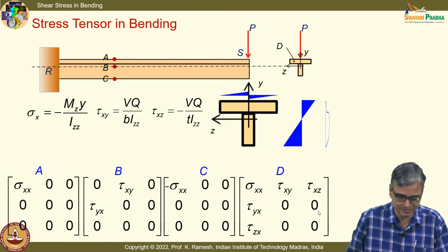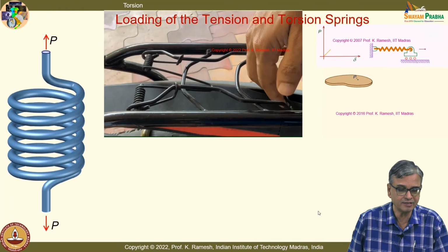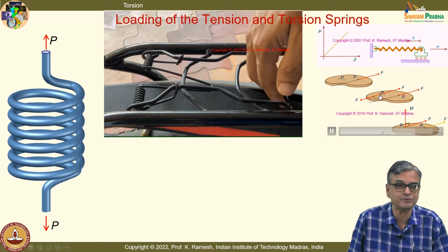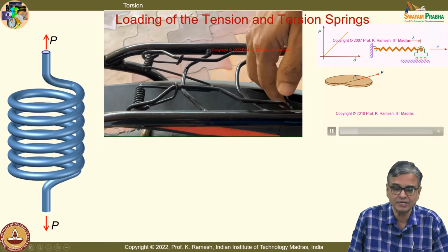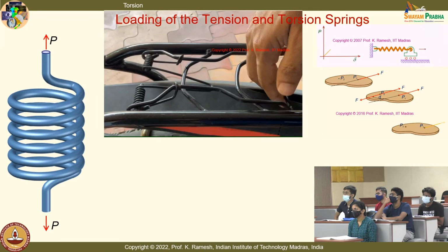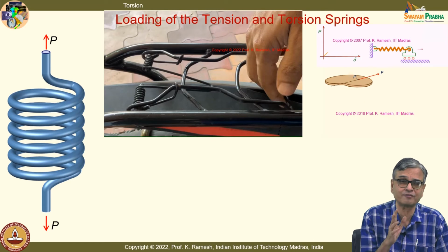Combined loading is the order of the day. Any simple problem has only combined loading. We learn them separately. And one of the concepts that I have said you lack is how to move a force from one point P1 to P2. If you master this, when I move this from P1 to P2, I need to have a force as well as a couple. You can comfortably write the bending moment diagram and shear force diagram.